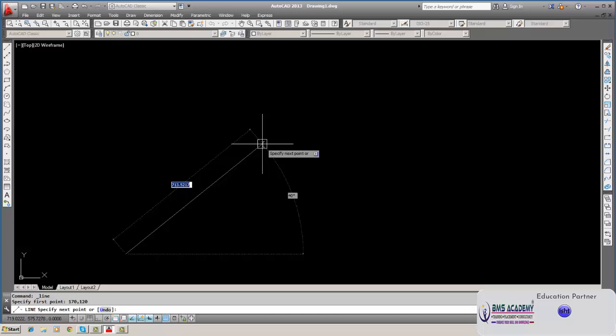Now we can enter a value, it is focused on the length, that is the blue color one as you can see. So this is focused here. It shows the length is now 730.527. If you click it here, the length of the line is 730.527. Suppose you want to have a different length, say 700. This is the point 700. And the angle shows 40.